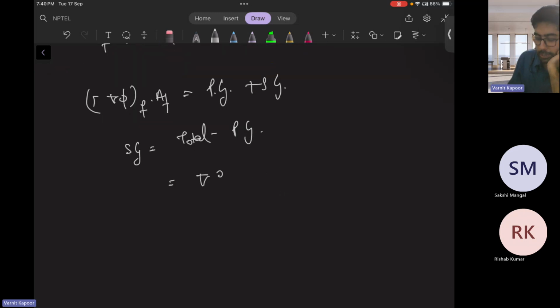But we don't know the phi values themselves, they are the unknowns. Now we are talking about calculating the value of the gradient of phi, which needs to be somehow computed on the face. So the calculation of the secondary gradient is reduced to the problem of calculating the gradient of phi.